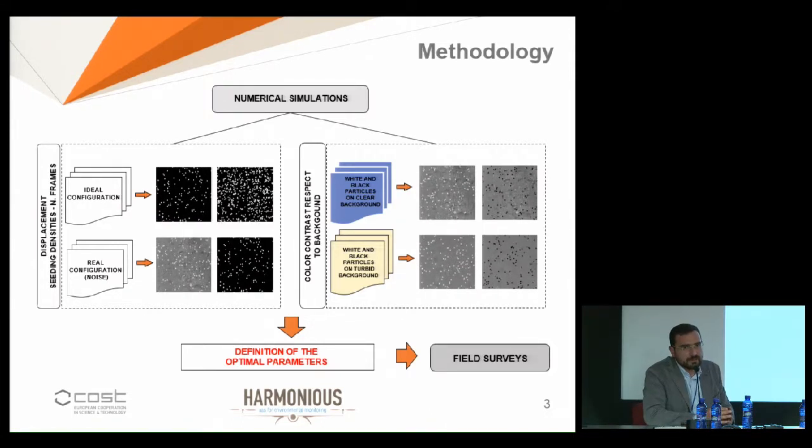By doing this, you can define a two-dimensional field of flow velocity vectors in a matrix. Of course, the number of vectors that you obtain is a function of the seedings, so the tracers that you have in your image. And the aim is to have a proper number of seedings able to sample the flow velocity over your domain.